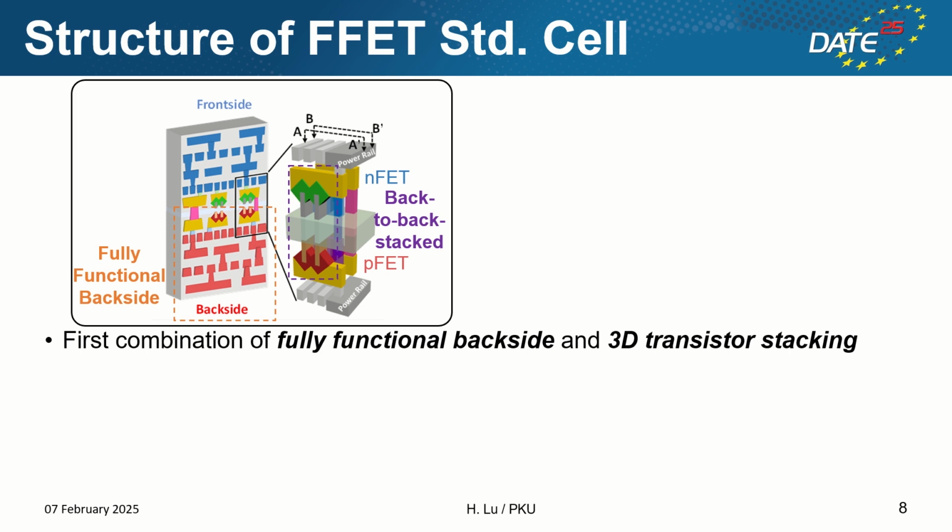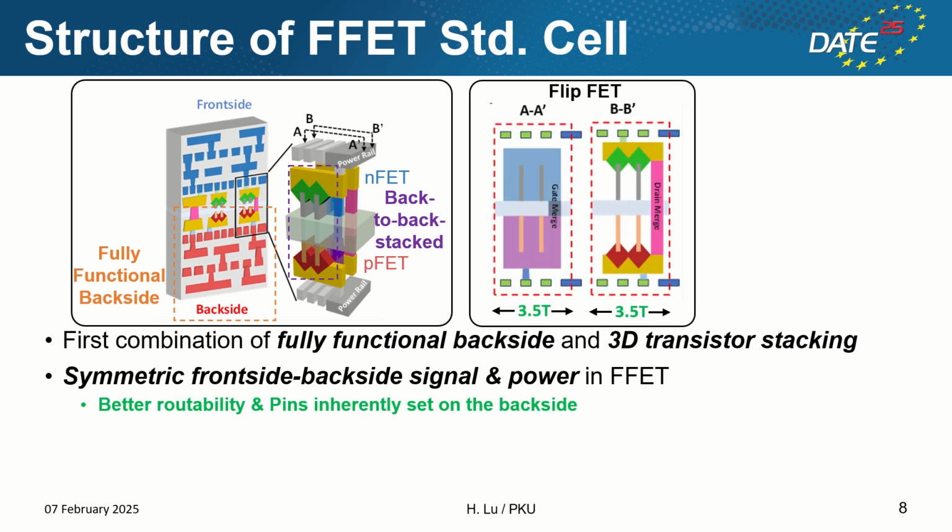The back-to-back stacked NFET and PFET in the FlipFET is a key feature different from the CFET. With symmetric frontside backside signal and power, the FFET standard cell features unique dual-sided inter-cell routing. The backside signals help improve the routability and enable pins inherently on the backside.